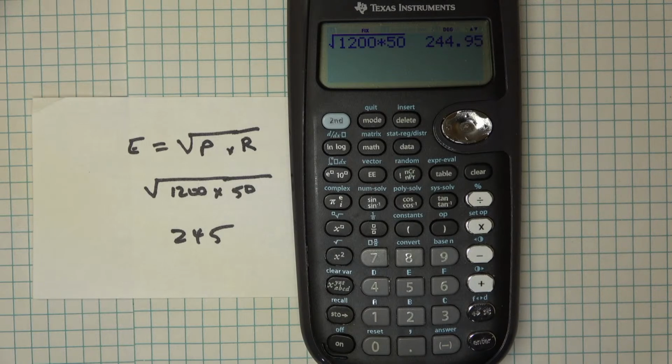So you're saying if I transmit with my linear amplifier at about 1200 watts into a 50 ohm transmission line out to a 50 ohm antenna, there's going to be 250 volts at the end of the transmission line? Well, right, yeah, if everything is matched, that would be true.